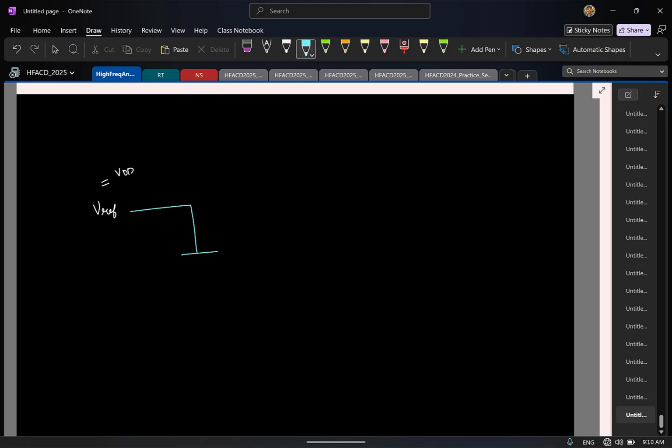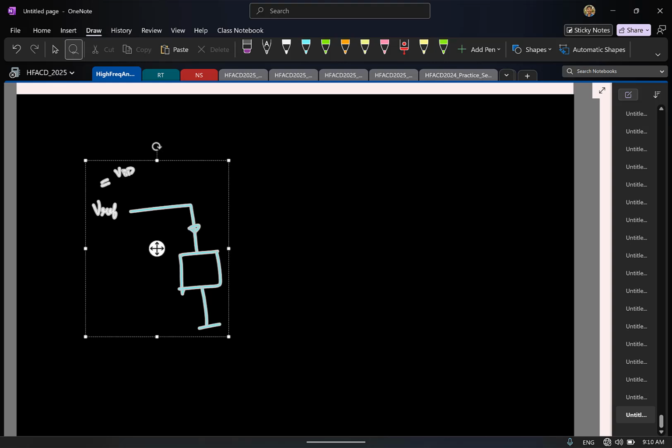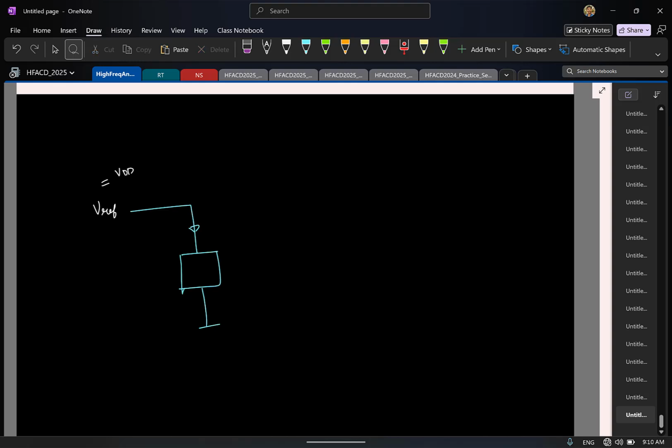Now let us say you try to connect it to your circuit like this. Your circuit will draw a lot of current, which means the band gap reference might not be able to provide it. So in a way, this is loading the circuit. So to avoid loading, what should we do? We should put a buffer. How do you make a buffer? Now you know how to make an op amp. Can you make better buffers with an op amp now? The unity gain configuration. So what we do is this: you take Vref and connect it in a unity feedback configuration.